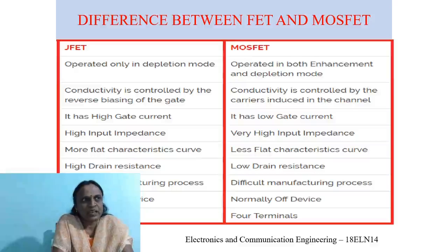In FET, the relationship between VGS and ID, the Shockley equation, that is the input voltage VGS and the output current ID, is used to define the transfer characteristics. We saw this at the beginning of session 4. It is a little more complicated, and not linear.